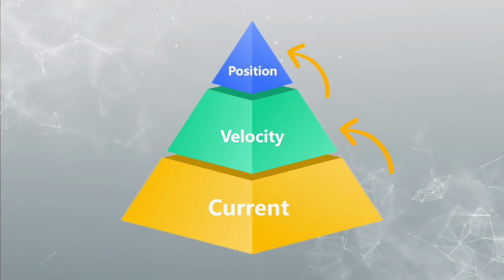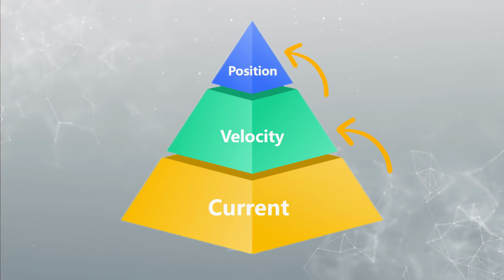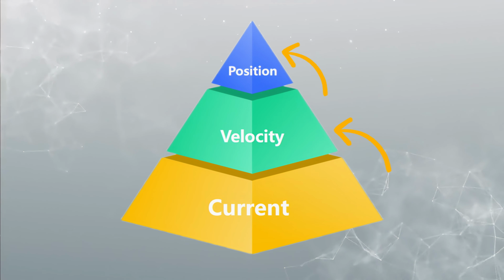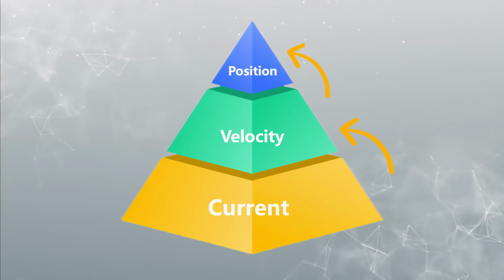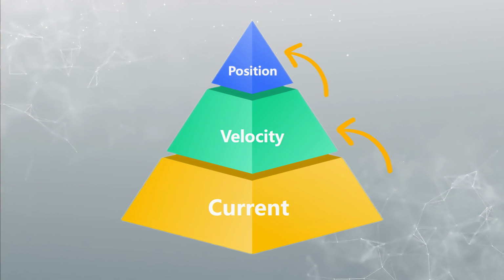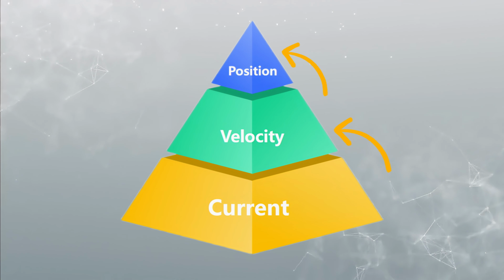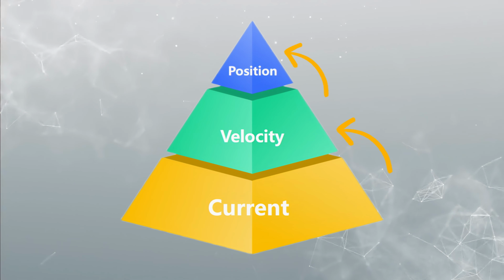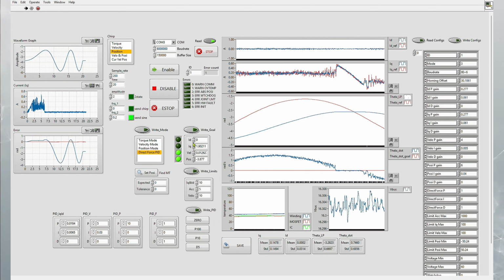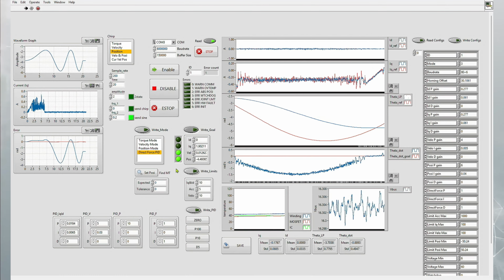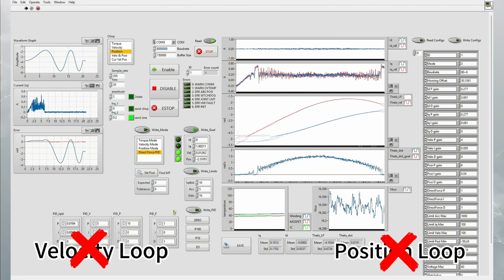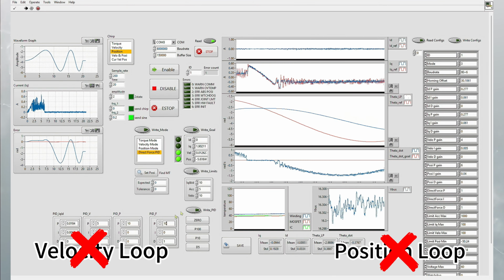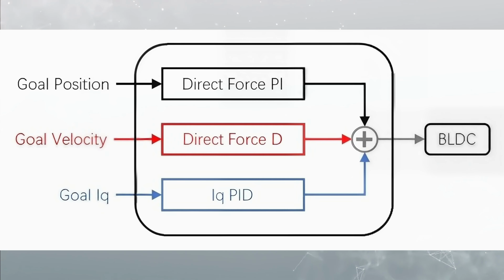Whether you choose to lock position D and rely on velocity P for damping, or prefer the convenience of dual loop position PD coordination over a stable velocity baseline, the goal remains identical: a responsive, crisp joint trajectory that matches your specific robotic application. Direct force mode bypasses traditional cascade loops to run an independent direct force loop. It allows Bear to simultaneously track multi-dimensional trajectories containing position, velocity, and IQ data.